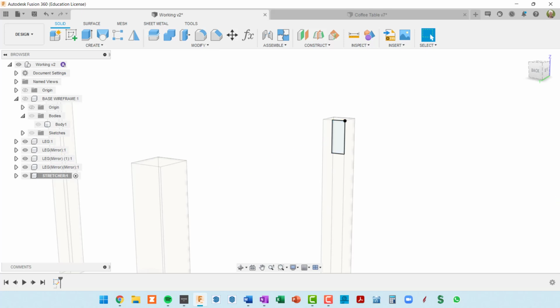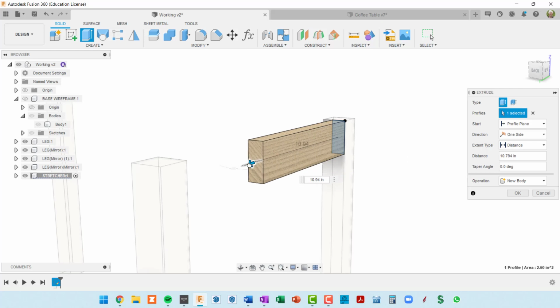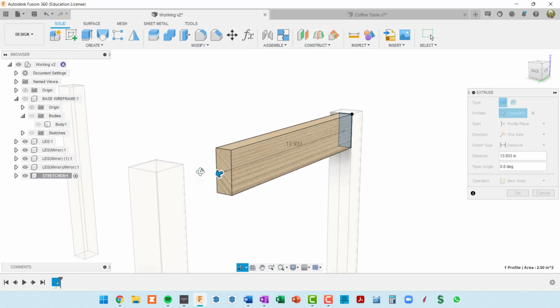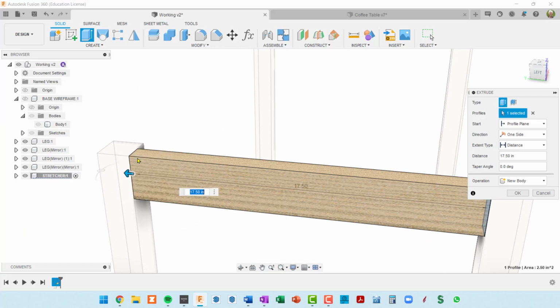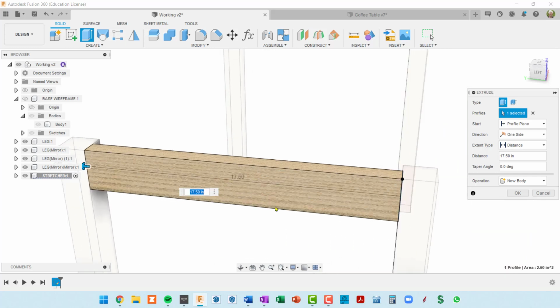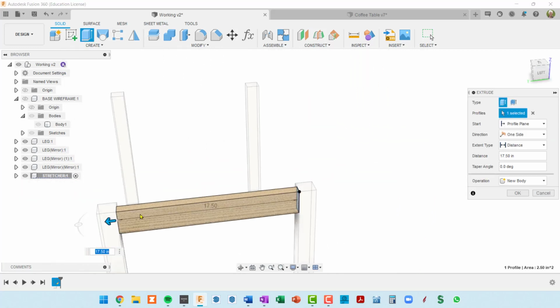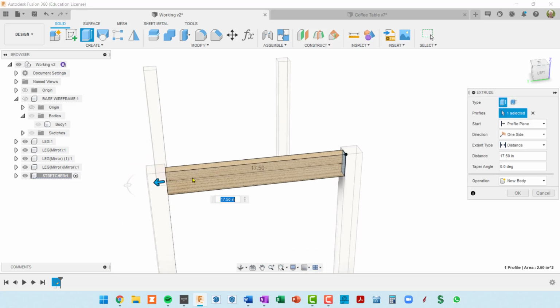So when I extrude, I can either extrude to a point here. As I'm extruding, I can click on this surface and essentially set the dimension that way. But I believe that's not going to be parametric. In other words, when the base width or depth changes, this length is going to change, and I don't think this is going to get the parametric stuff done. It'd be much more safe to actually put a formula in here to define this.